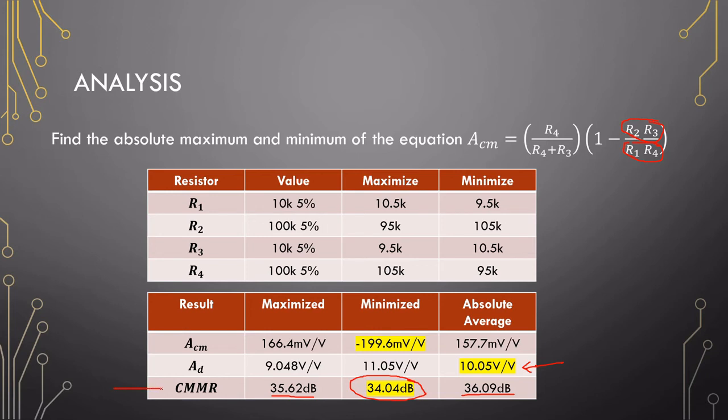So common mode rejection ratio, big thing when talking about medical equipment. So this value you want typically 80 dBs, 100 dBs plus, infinite if you can, but that is not possible with practical components. But that is what you're aiming for. So better CMRR, and you will be good. So let's go and have a look at the simulations for this.